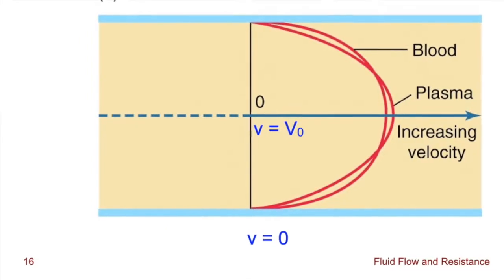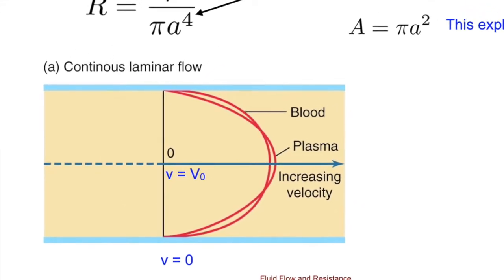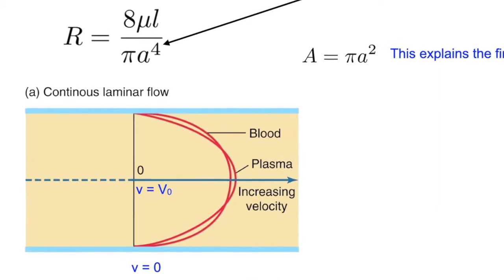And why is that? Well, to understand where that comes from, we have to think a little more about how blood or liquids in general flow through pipes. And just think about how that all plays out. And this is kind of interesting engineering because it has to do with the fact that at the boundaries of a pipe, we have a layer of fluid that's moving very slowly, maybe not even moving at all. Maybe it's just sort of stuck on the edge of the pipe. Whereas in the middle, we have a region of liquid that's flowing quite strongly. So we don't have consistent speed of the flow across the cross-section of the pipe. And that changes things. Then we don't have a simple dependence on the cross-sectional area.